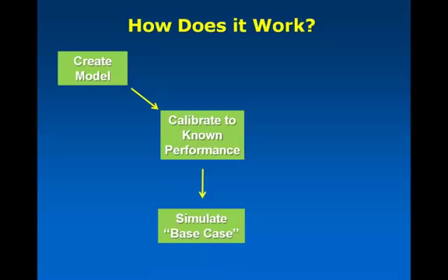Then what most people like to do when they're investigating the behavior of a wastewater treatment plant is to simulate what they call their base case. So this is sort of the standard running, normal, typical operation of your wastewater treatment plant. And quite often, particularly here in Canada, we do a summer base case and a winter base case, given the wide range of temperatures that we have to deal with here.